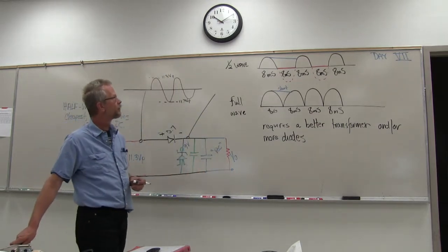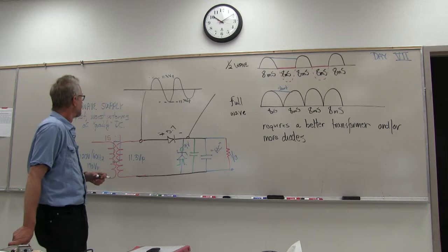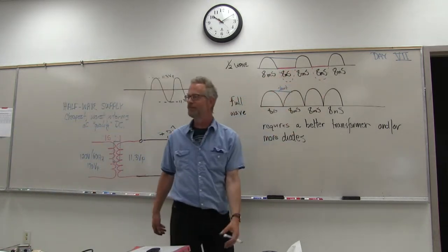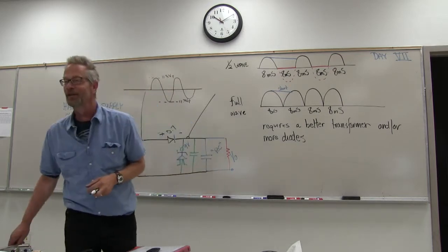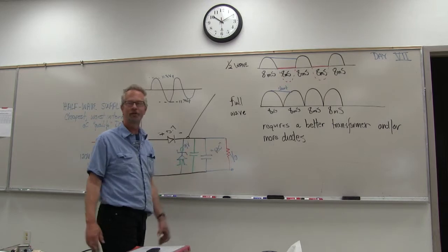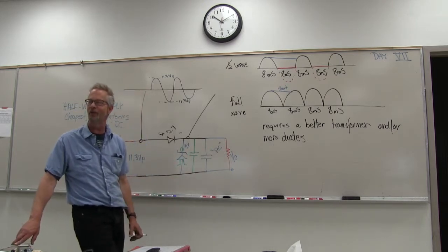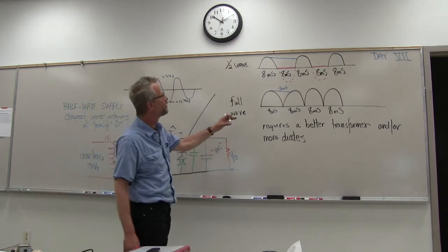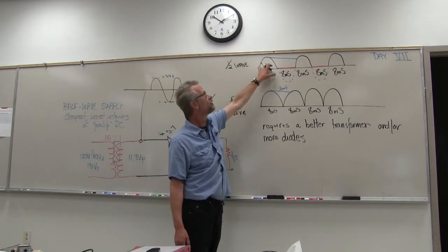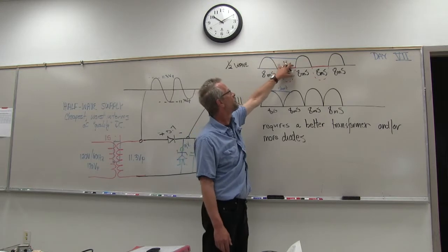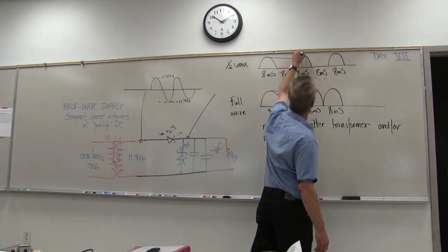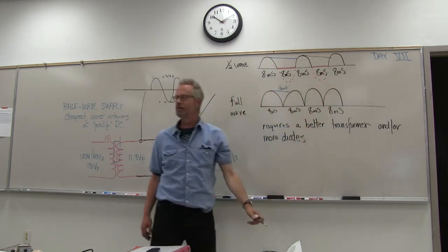Okay? That's why I refer to half wave as being the worst, because there's such a huge gap between energy bursts, if you will, that the capacitor basically has to supply all the power to a load. So in a sense, if you really wanted to look at it another way, what we're really doing is charging up a battery. A capacitor and a battery are very similar. Charging up a battery, discharging that battery. Charging up the battery, discharging that battery. And every time we discharge that battery, voltage goes down.